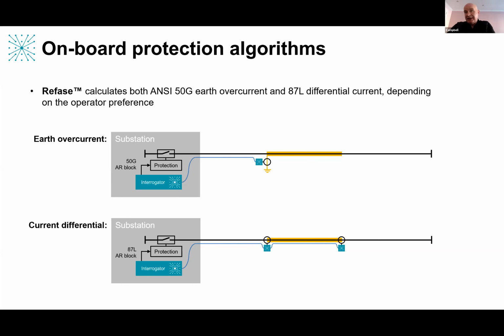Some cables are three-phase and either the sheath or there's a separate earth core. Some it's three individual phase cables itself. So differential will capture everything. Earth overcurrent will capture those that involve earth. So I think that's probably the trade-off between simplicity and cost on the one hand, and the reliability of it catching every single type of fault possible.